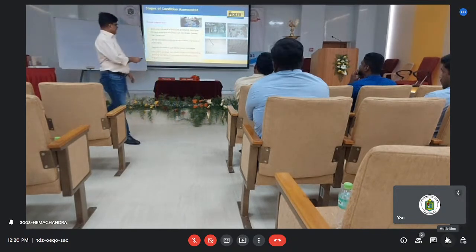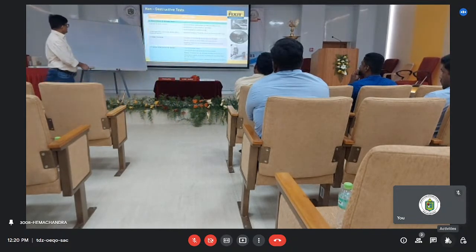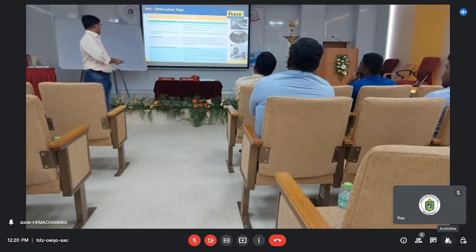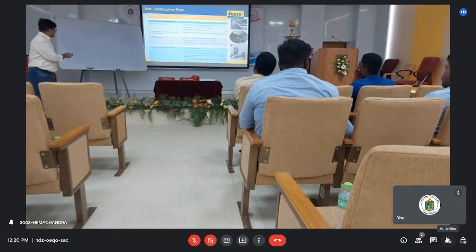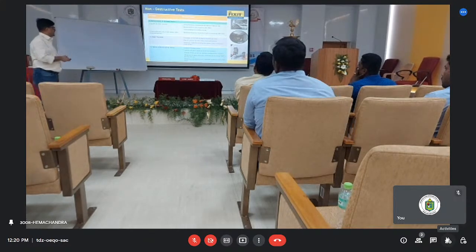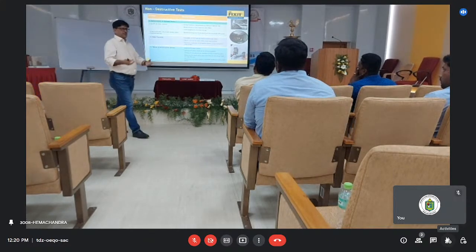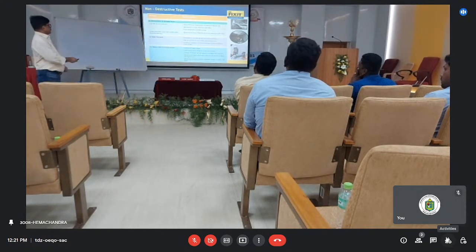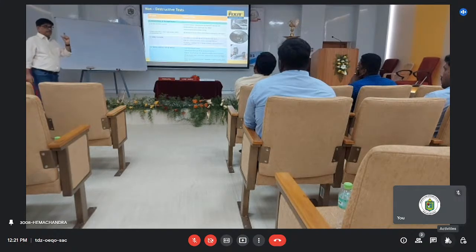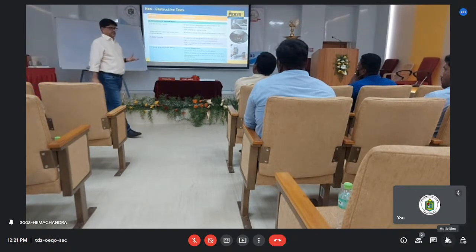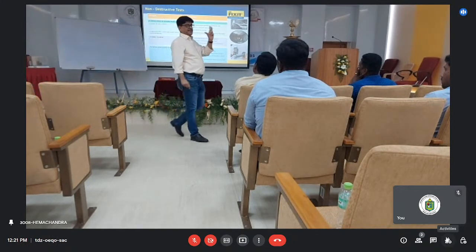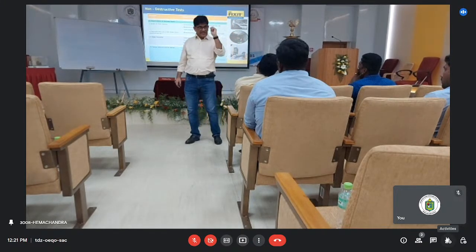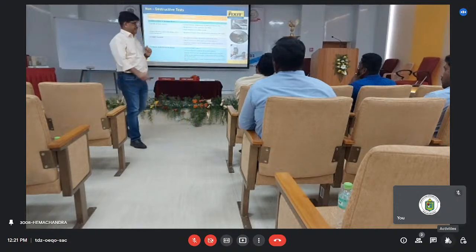Next, coming to your tests. What tests do I have to do? If there are any deficiencies in the concrete quality, I can check with a proper tapping hammer. I can also check how much my cover depth actually is. We talked about cover depth: in my podium, how much cover depth have I actually provided? We can check that with a cover meter.